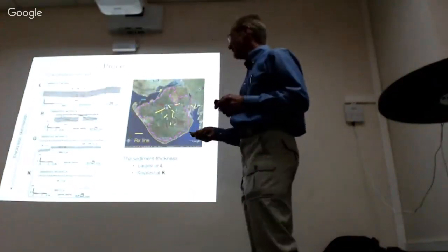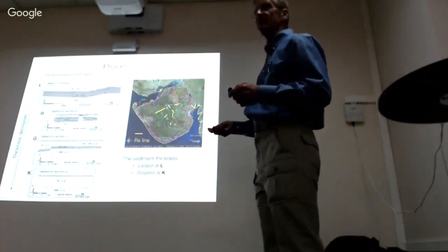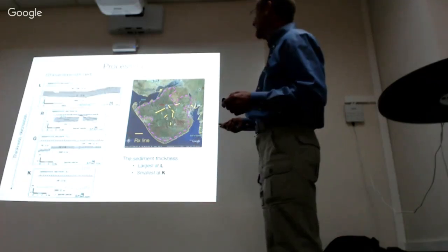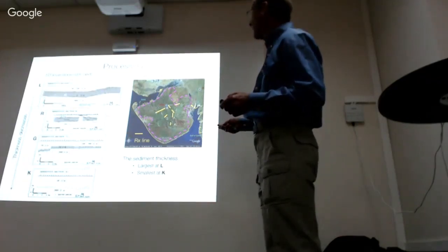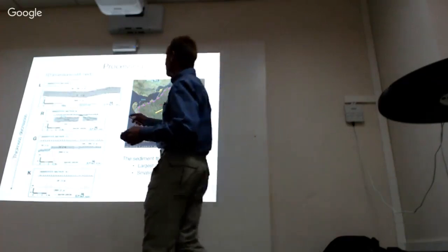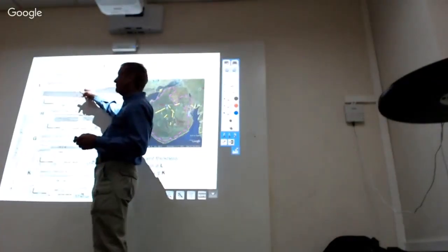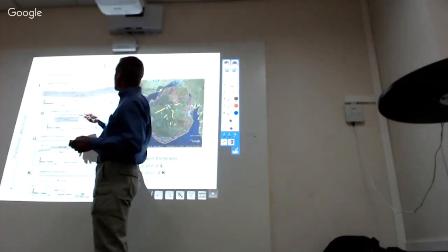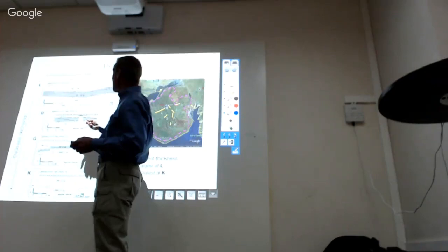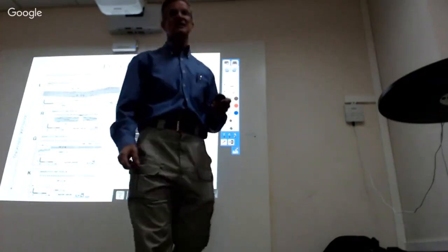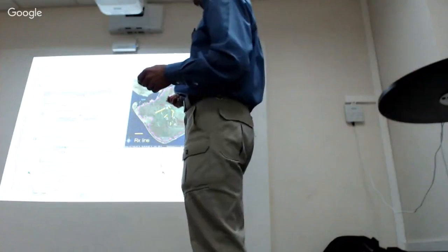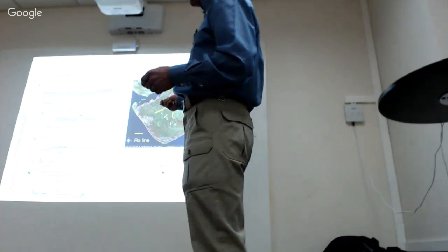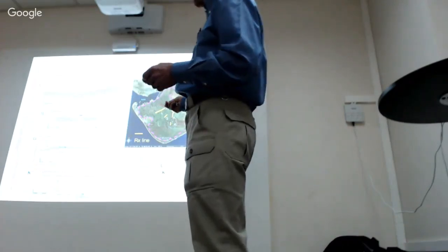So the processing here was basically a 1D inversion. Here is line L along here. Along that line, we have an upper region of basalts from 80 to 140 ohm meters. That's a little bit more than a kilometer thick. Then this dashed line or grayed out zone here is sediments. That's a low resistivity, 16 ohm meters. And then the bottom is 3,000. So this showed a thickness of sediments there of about a kilometer.